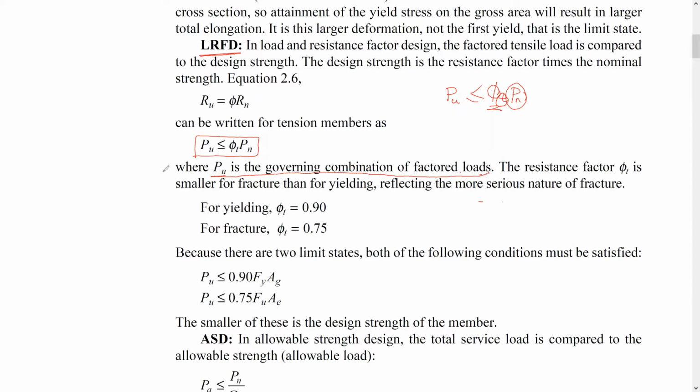If you remember, we do have load cases. Case number 1, case number 2, and so on. And right now you have to pick the largest factored loads, meaning the largest value, and compare it with the design strength.